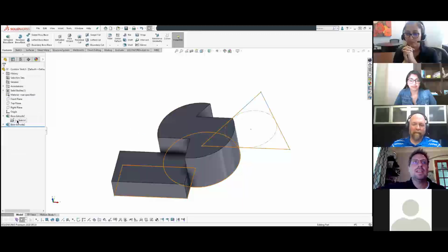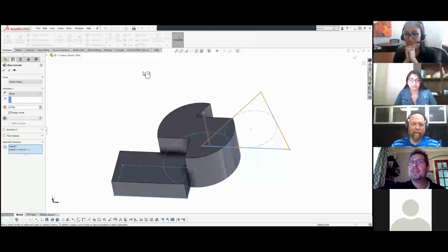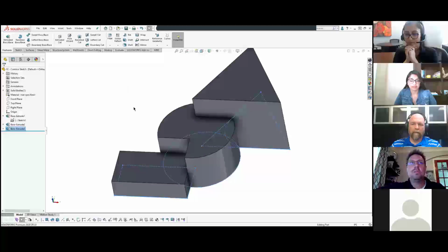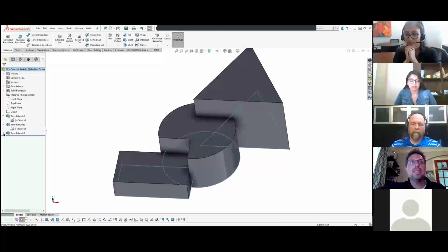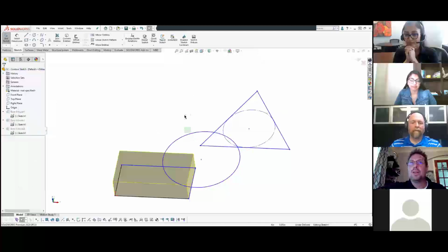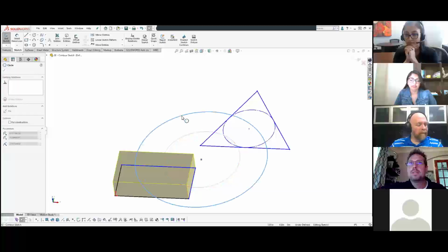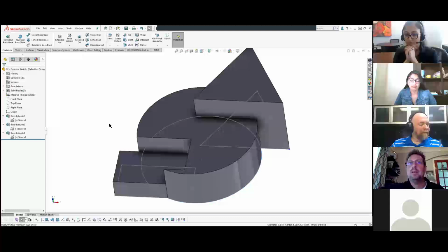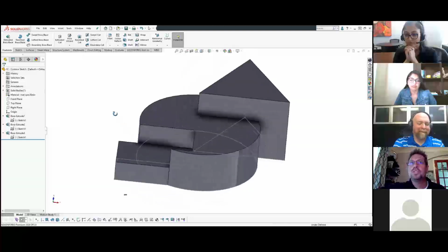Then we can do the exact same thing. We'll do a sketch, pick on the sketch, and do an extrude. This time I want to get the whole rectangle, so I'm going to pick on the outside of the rectangle. That's going to be a contour. I'll make that one big as well. Again, the main thing is that you're using the exact same sketch over and over again. So if you decide to make a change, if I edit the sketch and make this circle bigger, there we go, and finish out of the sketch, everything updates appropriately with what you've selected.